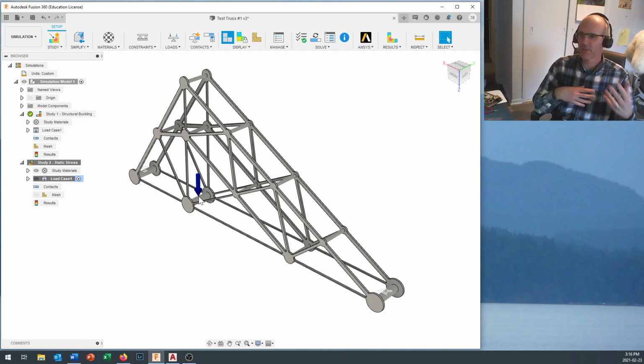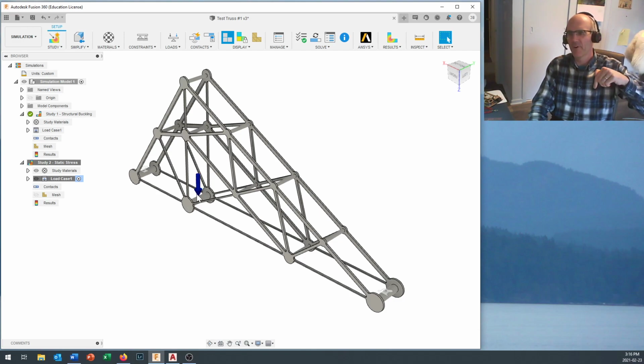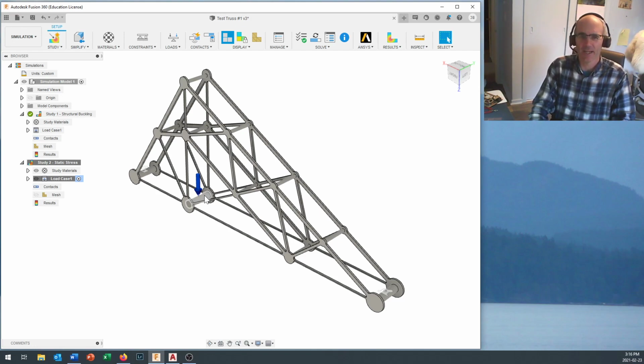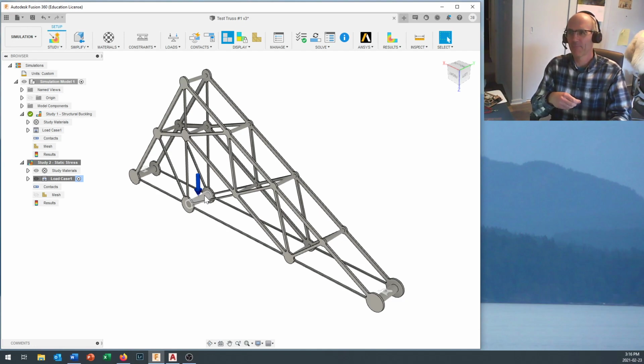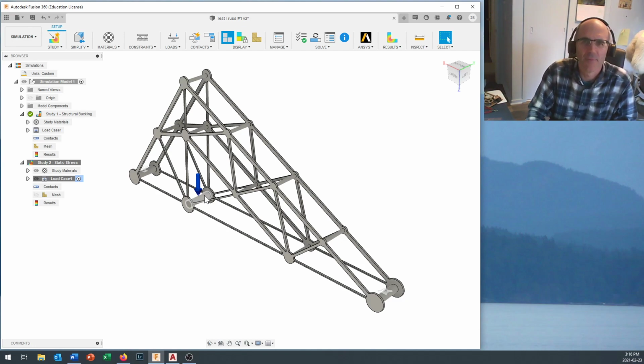Now, because this is your first time using Simulation in Fusion 360, I have simplified a few of the things that we're doing right in here. I've skipped over getting the absolute perfect material coordinates in there. And as you can see when we do our testing, our loading jig is slightly different from always providing a perfectly downwards vertical force distributed evenly across this member. It's close enough that these results are going to be meaningful to guide your design, but if we're off by a couple of numbers, that's okay.